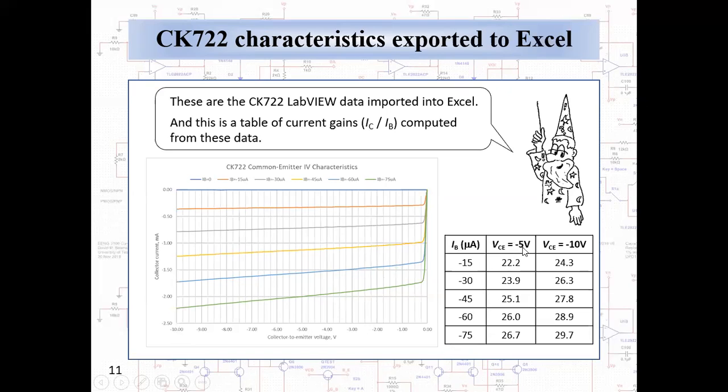The values we get range from a little below 30 down, at the low end, to 22.2. Now these values are actually quite low compared to modern transistors, where I would expect modern devices to have current gains of well over 100, maybe into several hundreds. But for the alloy transistors, which was the technology of the 1950s, these are respectable numbers.